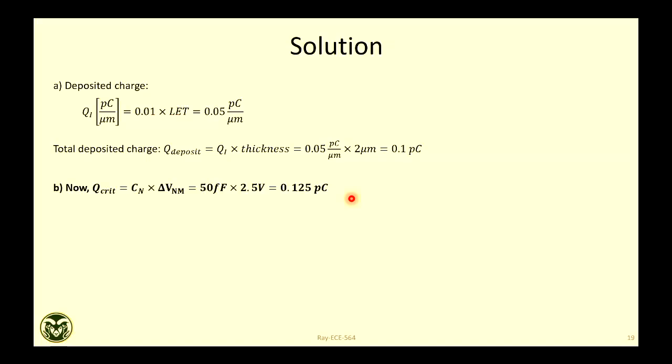No upset, if you read immediately after the strike. You are already at a lower charge, but you might be reading later, after you refresh. So it all depends. Just after the strike, you can say there is no upset. It depends on when the strike is happening. If the strike happens just before refresh, then no upset. It also depends on the initial condition of the capacitor. The detailed actual behavior is a little complex, but for problem solving, we will make some simplistic assumptions. If you are reading just after the strike, will there be any upset? The answer here is no upset.